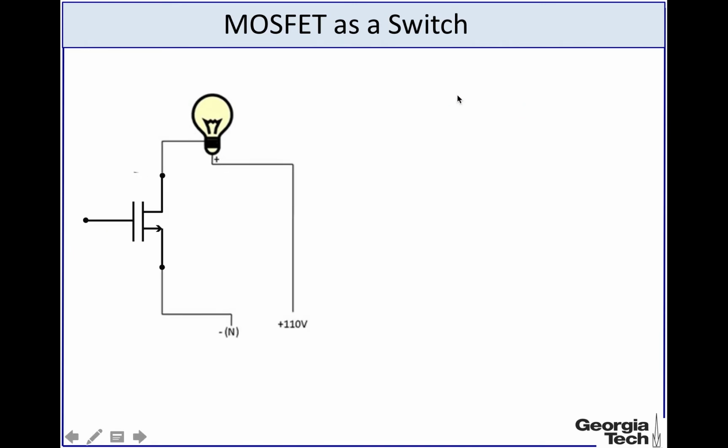All right, so again this figure here, I'll just say the same thing as we said in the previous slide, and we'll want to talk a little bit more about the concept of threshold voltage. As we have said, if Vg equals 0, then this will be an open circuit, so this circuit will look like this, and it is connected to positive and negative here, so it's open here. So the current that flows through the circuit here will be 0.